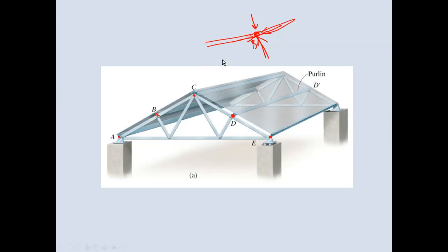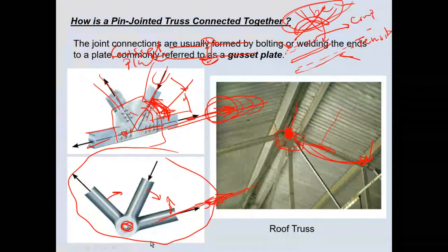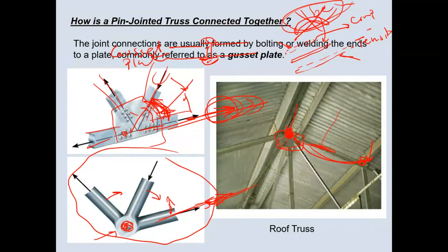That can be seen in the previous figure. So if there is an external force at the pin, that external force is distributed between this one, that one, that one. So you are not directly applying this force to the members. You're applying that to the pins, that bolt, and the bolt would distribute this in an elongation mode or shortening mode of each individual member.